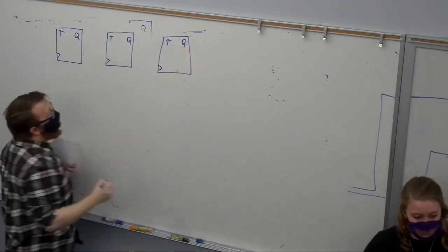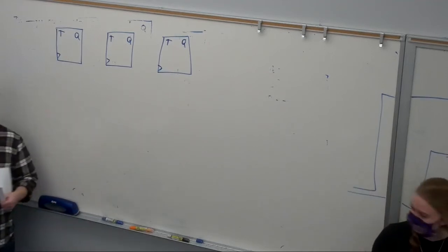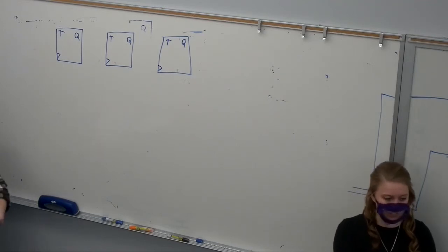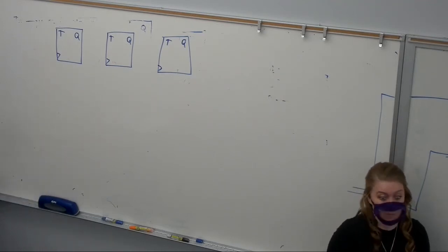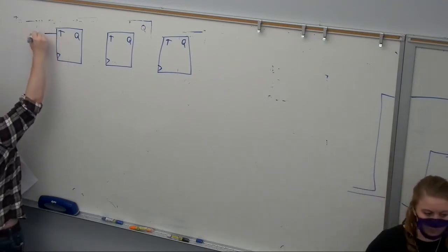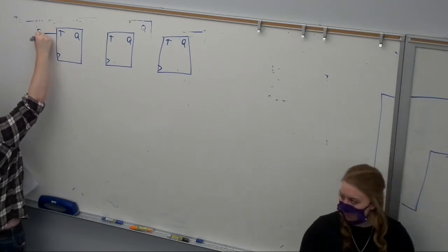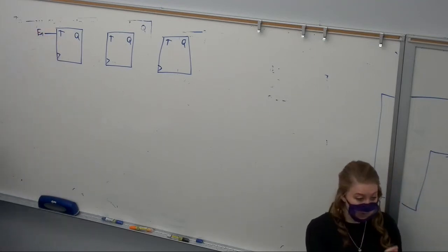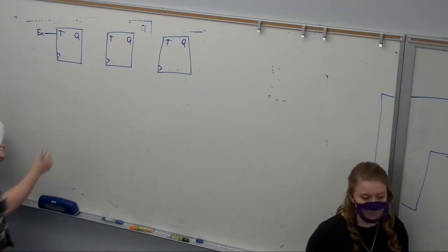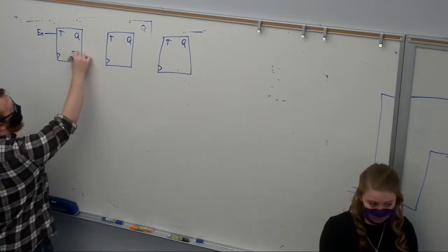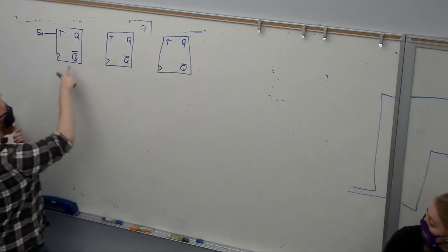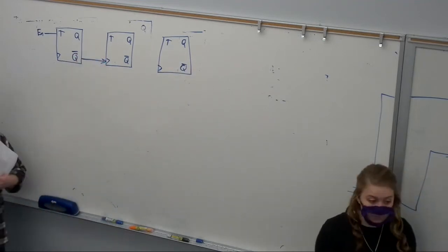And I'm going to be lazy and try to make this an asynchronous counter, so I don't have to deal with that extra logic and I can do the simplest use case. The first counter is just the enable. If we want to count, we assert enable. Then for the up counter case, we would take Q bar and feed Q bar into the clock, right? Do you remember that?